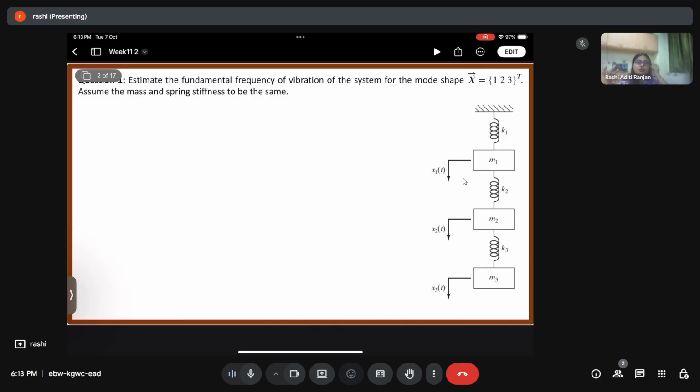So different mode shapes correspond to different frequencies. Exciting the system at that particular frequency is going to give us the particular mode shape, correct? This is what we know. Now, we know that the mode shapes and the mode frequencies are related to each other, correct?